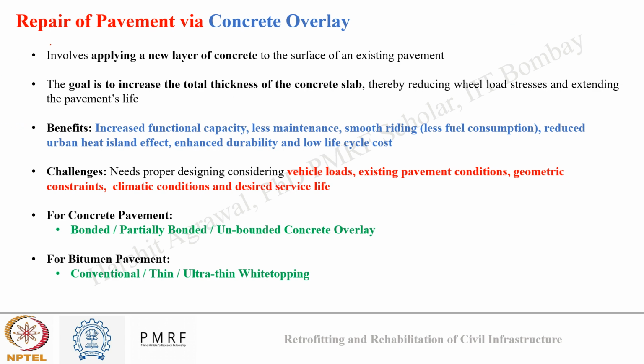This technique is more often used for retrofitting rather than repair, though in some cases it can also be used for repair. But mostly for repair purposes, our first primary task is to fill the cracks either by grouting or shotcreting, based on the extent of damage.